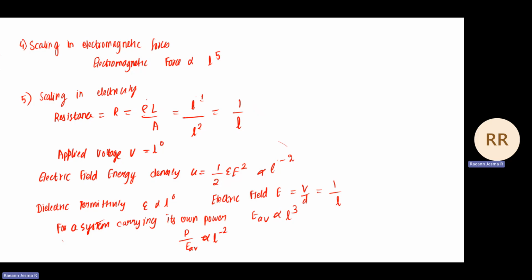Say if you want to make a motor, then you would prefer using electrostatic force for actuating the motor instead of electromagnetic force, because the electromagnetic force is very insignificant at micron scale when compared to higher scale objects. Thank you.